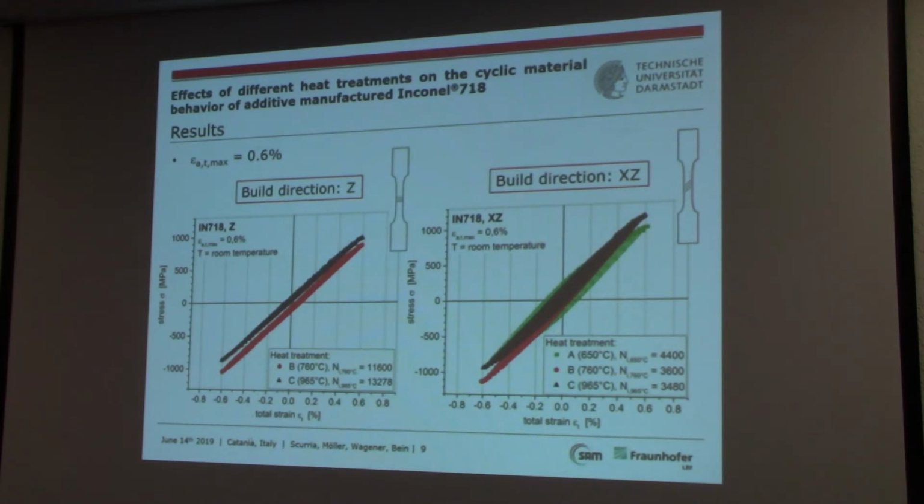So we definitely have an enlarging of the hysteresis at the same maximum strain amplitude with two different build orientations. This can be due both to the fact that we are building at 45 degrees with respect to the bed of powder, and to the fact that we removed superstructures, so we will have local plasticity here, for example.